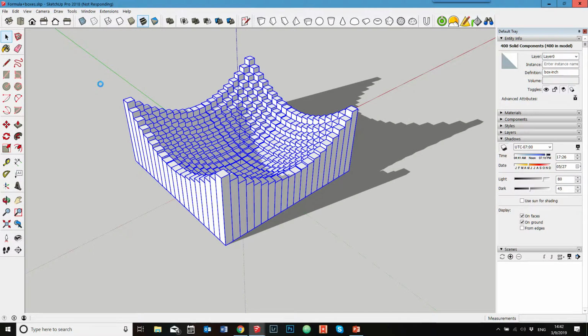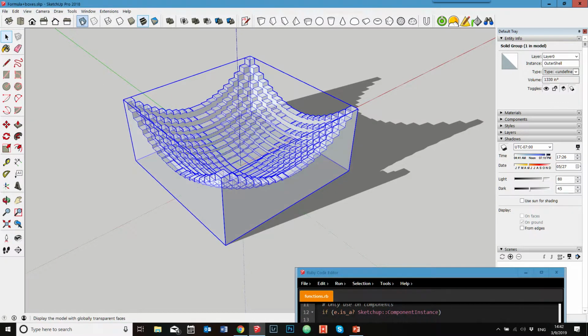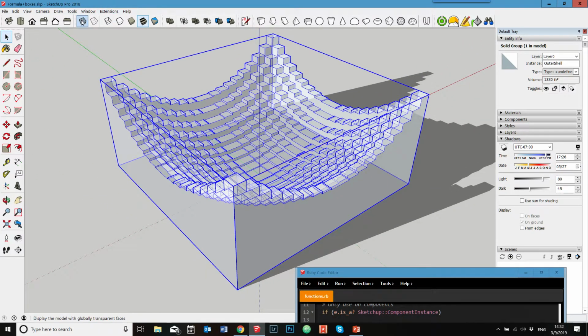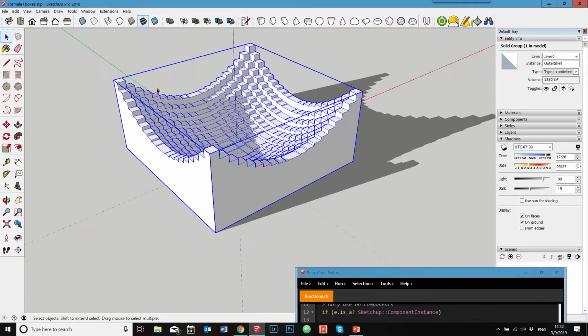There are different tools that you would want to use to check whether something's 3D printable. And if you do this from another CAD software that is already a solid modeler, then you don't have to do that because it's already solid. But nevertheless, that would be the process here. So now you see nothing, all of the lines went away. If I actually turn my X-ray vision on, right here you can see this is what's called now a watertight solid or a manifold.